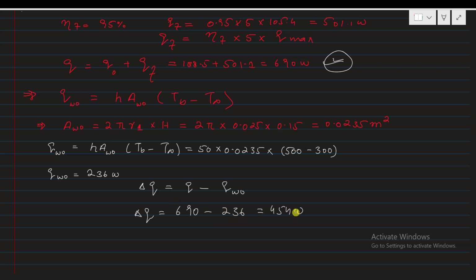This increase in heat transfer is very important to prevent the engine seizure. That's why extended surfaces like fins are very important when your concern is to cool down your prime system. Our engine cylinder is the prime system. We need to decrease its temperature, so that's why we provide fins over it.